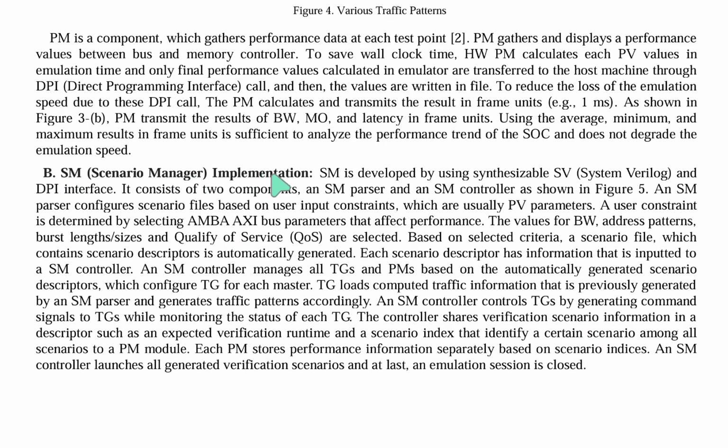SM, Scenario Manager implementation. SM is developed by using synthesizable SV, SystemVerilog, and the DPI interface. It consists of two components, an SM parser and an SM controller, as shown in Figure 5. The SM parser configures scenario files based on the user input constraint, which are usually PV parameters. A user constraint is defined by selecting AMBA AXI bus parameters that affect performance.